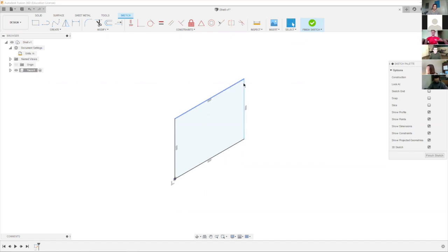So you'll notice that we have two black lines here and two blue lines. The reason is that the black lines are locked onto this point. However, the blue lines are, the way you could put it, floating off in space right now in this rectangle, and we can move it around however we want. To create a strong model and form, when you're creating any sketches, you want to constrain them as much as possible so that we don't have any of those blue lines.